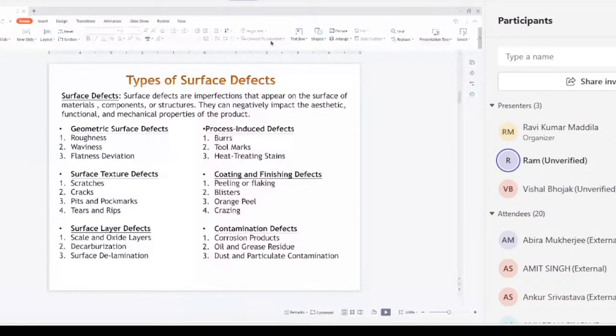Now, the penetrant is stuck inside the defects. This is viewed under UV light or a fluorescent light. UV light is typically used for fluorescent penetrant, and visible light for liquid dye penetrant testing. So you see any kind of surface defects which are open to the surface, like a crack or porosity, or gaps. These are all the defects you can find.